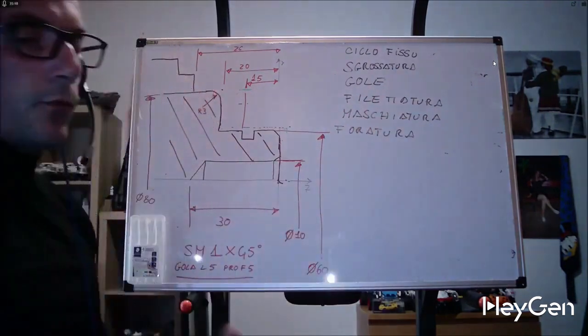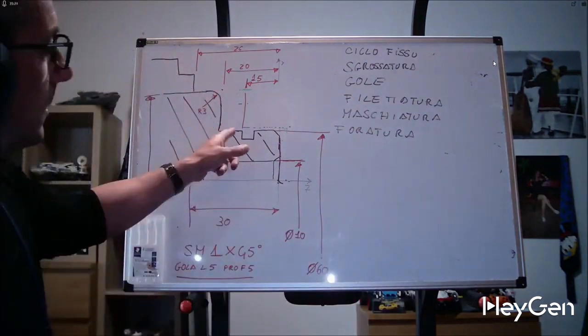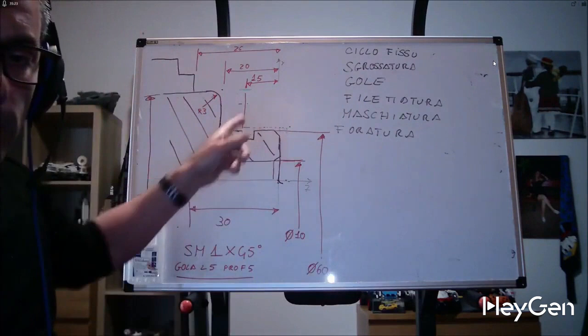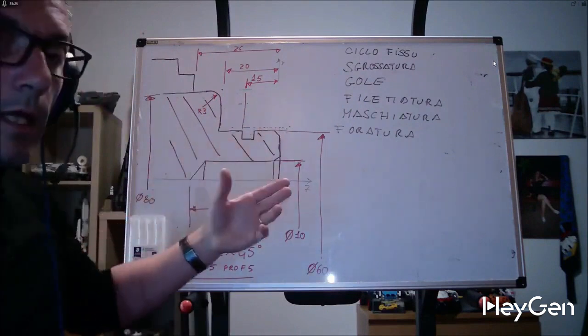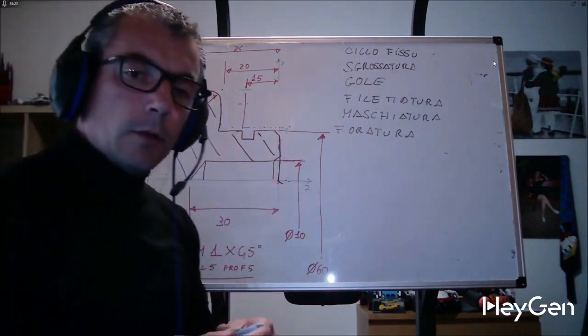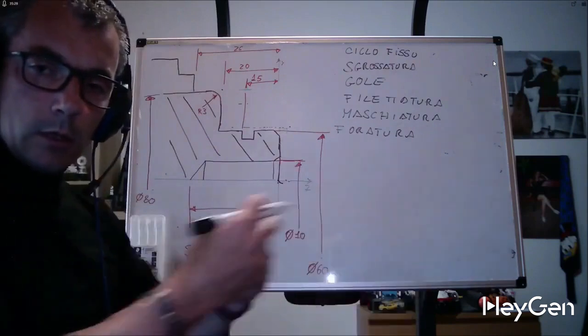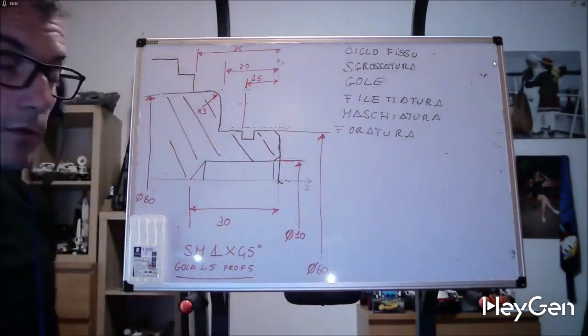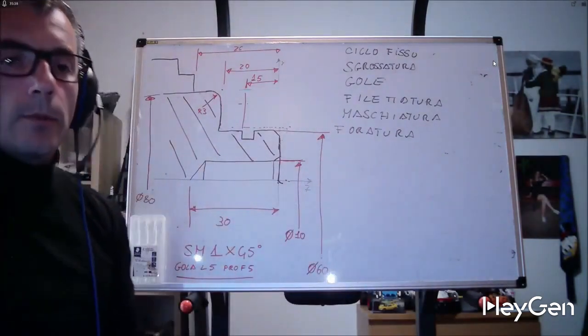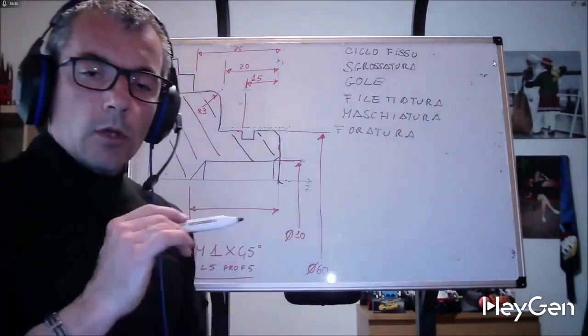Also, these fixed cycles for threading, once you provide the length, pitch, diameters and depth of cut, will handle the back and forth for you. Tapping cannot be programmed.